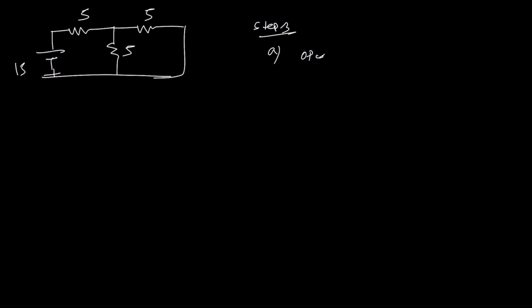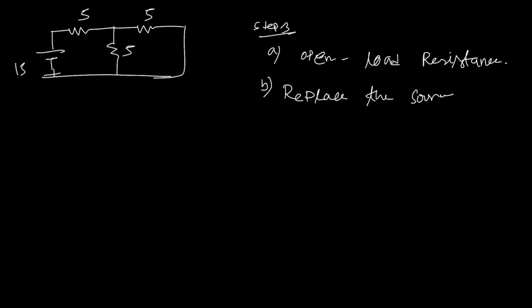Open the load resistance. Step 2, remove all of the sources, or we can say replace the sources with their internal resistance.